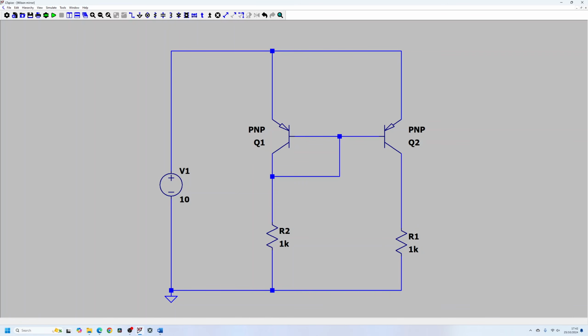And one of the disadvantages of this current mirror is that if you want the current mirror to work perfectly, these 2 transistors Q1 and Q2 must be perfectly matched in terms of characteristics, specifically their base emitter voltages. Obviously, in a real world circuit, that's going to be different. So the transistor mirrored currents will be slightly different, and the difference will depend on your variation between the 2 transistors. Another problem that we have on this circuit